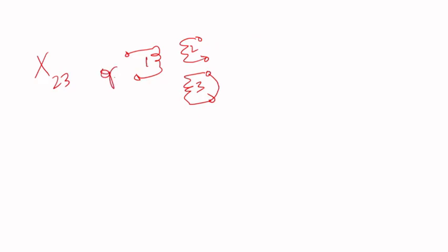This will remain open because it's not involved. I'm going to energize winding 2. So kind of the same principle, and when you do this test, you will measure, again, losses, because you're going to have a watt meter connected. You're going to measure the voltage that was dropped, and obviously you apply the rated current.